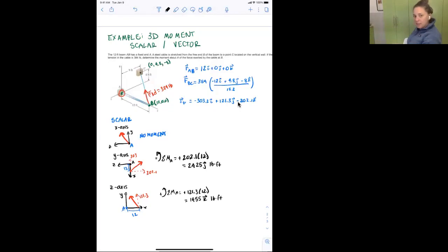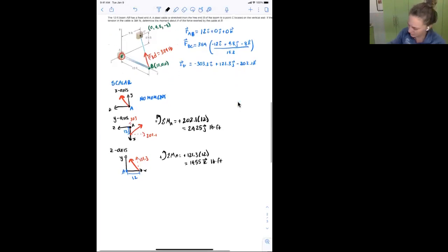Like your y-axis is up, this door twisting around, that would be around the y-axis. But at the same time, there's rotation as if you were lifting up a trap door. So both of those are happening at the same time. And that's what the scalar method is showing us. Okay, let's solve it now using the vector method.